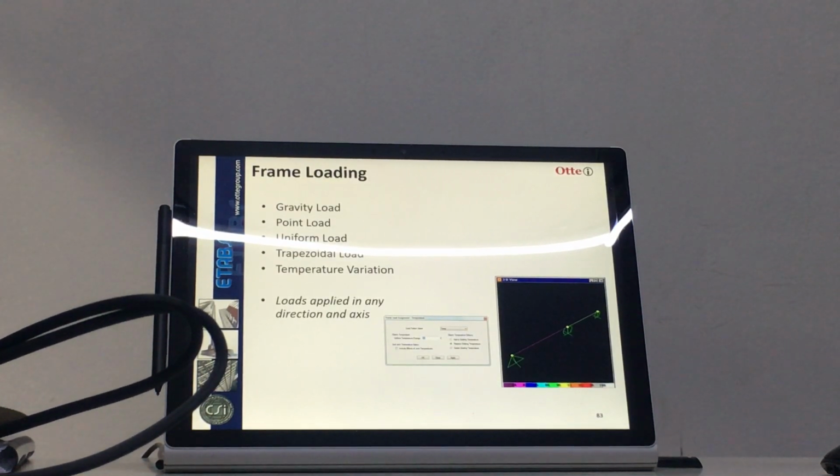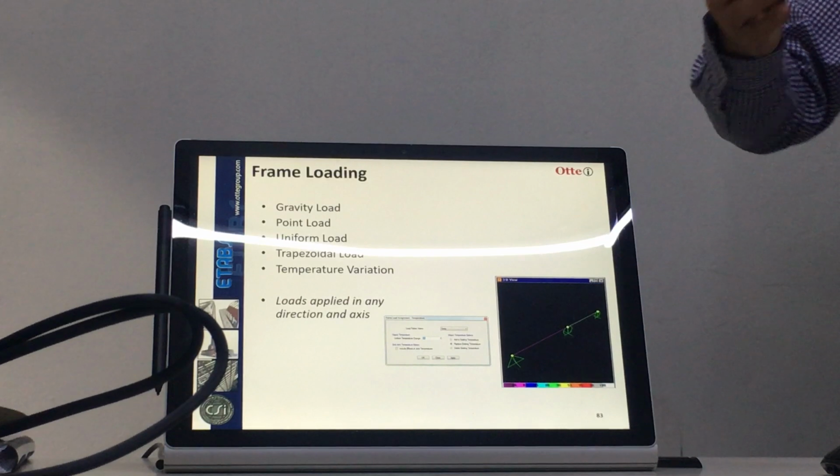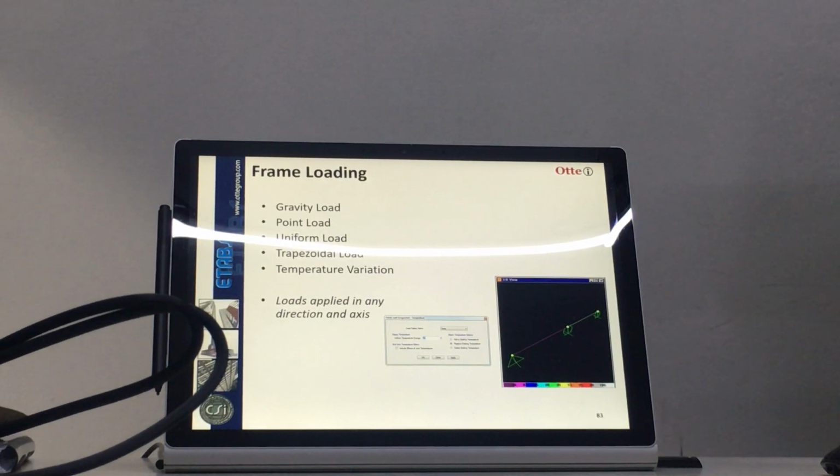And then we can have different kinds of loading on the frame. But typically in Etabs, most of the time you don't load the frame, but in your steel maybe different. Because when you have a purlin, you don't model the roofing, right? So you have to find out the loading and apply it to the purlin, right? So you still have to do loading. But in a normal building like RC, most likely the only time you load a beam is when the beam is supporting a wall. Or else you use the floor to transfer the load to the beam.